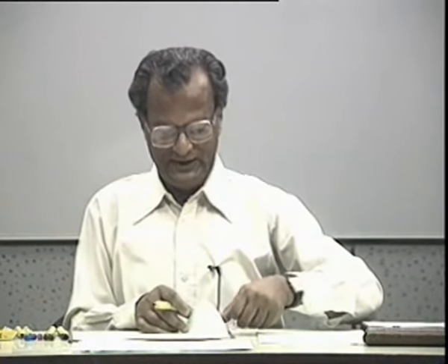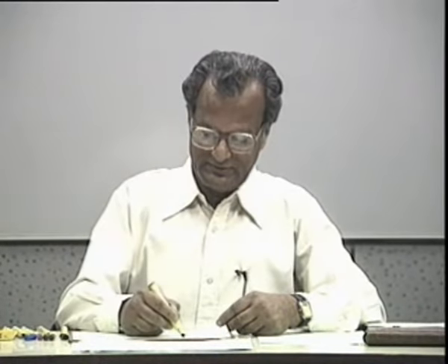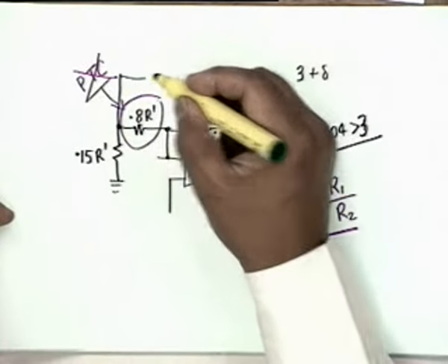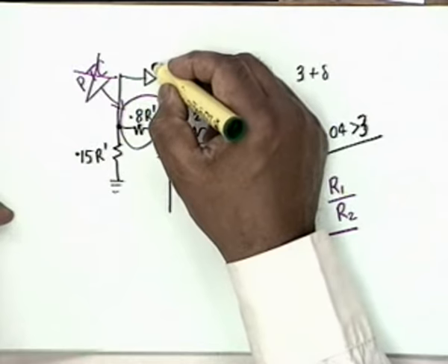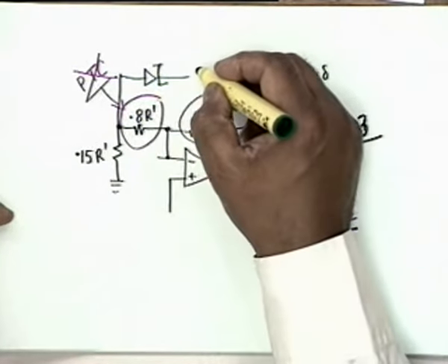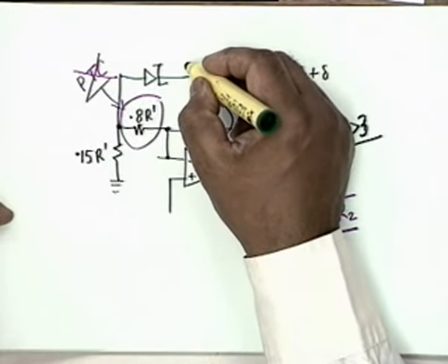They are positive temperature coefficient. Okay. One of the commercial Wien bridge oscillators does not rely on this only, it uses in addition two Zener diodes in parallel with these two. That is, one of them is like this, a very interesting concept.